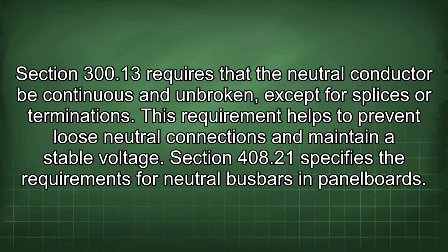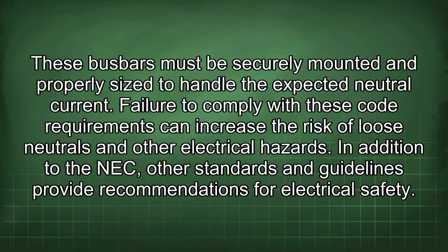Section 408.21 specifies the requirements for neutral busbars in panel boards. These busbars must be securely mounted and properly sized to handle the expected neutral current. Failure to comply with these code requirements can increase the risk of loose neutrals and other electrical hazards.